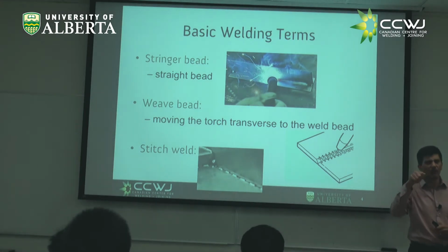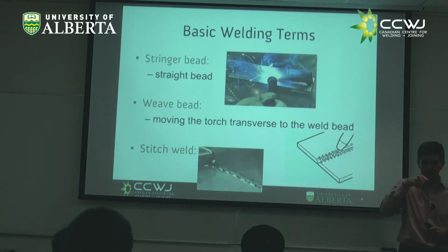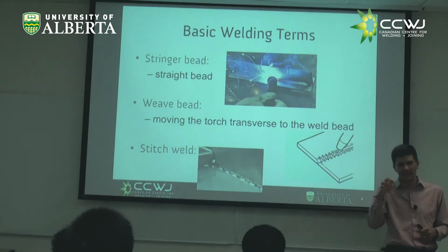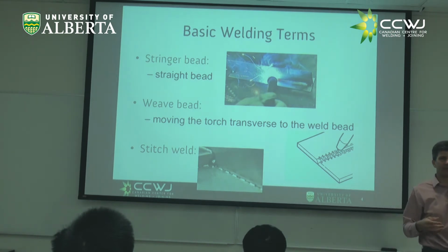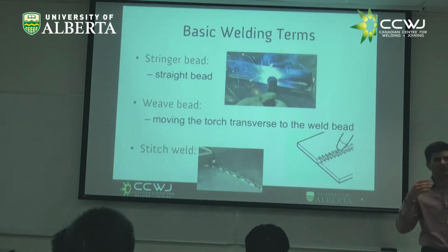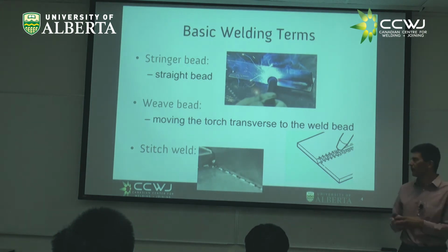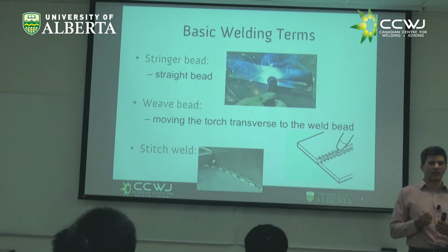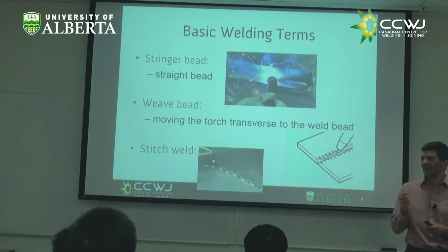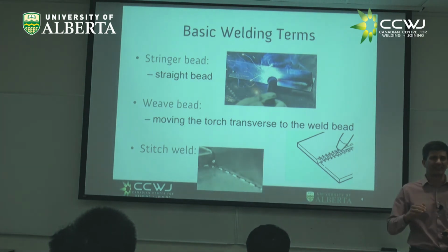And they have many ways of weaving it. They can go in zigzag, they can go back, they can Texas lace. I don't know because I'm not a welder, but if you talk to the actual welders, oh, they will talk with so many words and so many things about this weaving. The good thing of the weaving is you can fix a mistake because you always come back. But in a stringer bead, no chance.